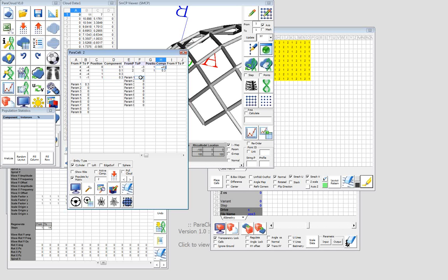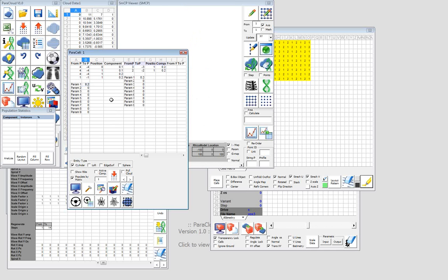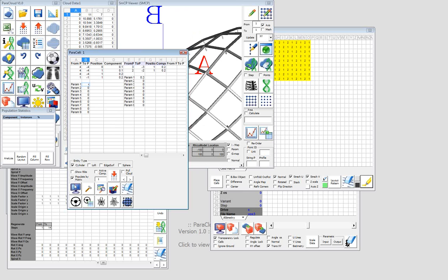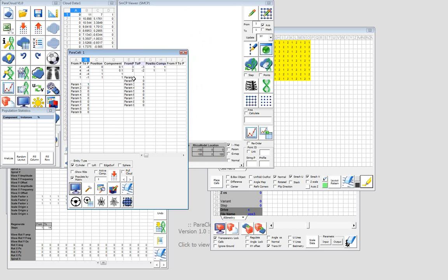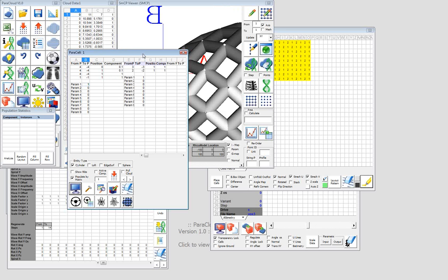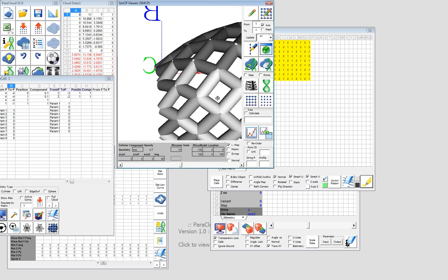And this is simple Excel linking that we can do. If we change this value here, we can even take this and nest this thing to this value here. So changing this value here to, let's say, 0.2, and preview that will change our design geometry. If we want it to be very thick, we can change it to 1, so you'll see the big difference, and so on. Now, I want you to chain this, but read different values for this parameter.